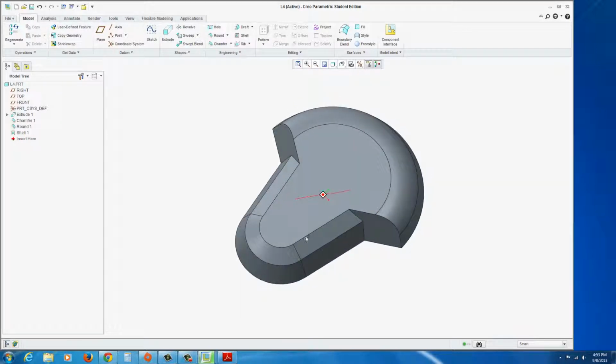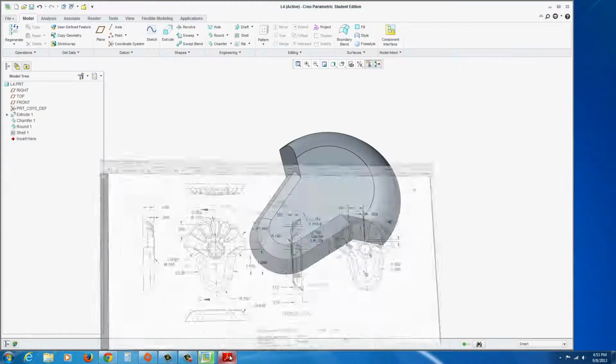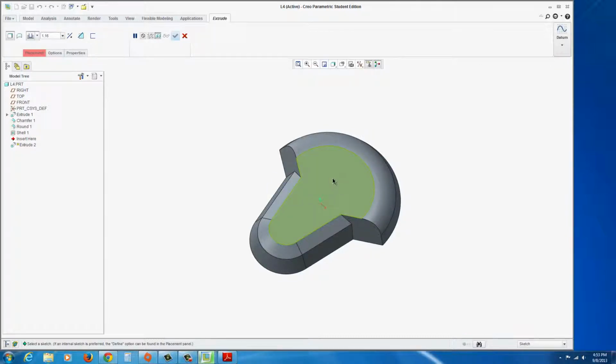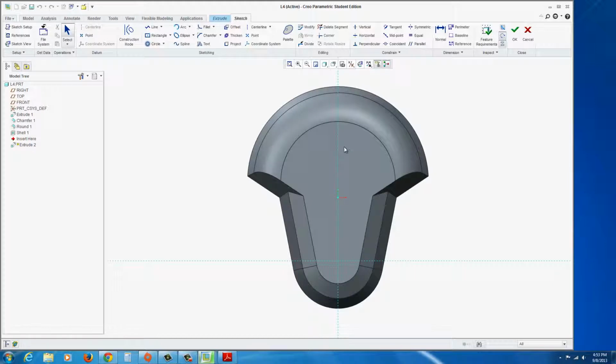Now at this point, we're going to put in these little holes in here, these pockets. So we could start with the extrude, select this face right here in front. Make sure you go normal to. Remember, you could always go to AB and go to front as well if yours isn't automatically set to go in that orientation. First, start off with the center line and draw a new center line in the center.